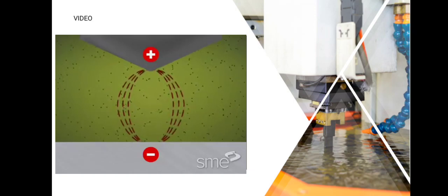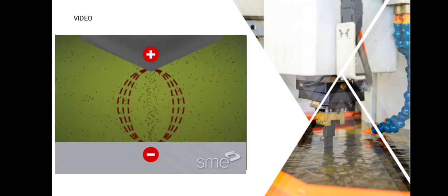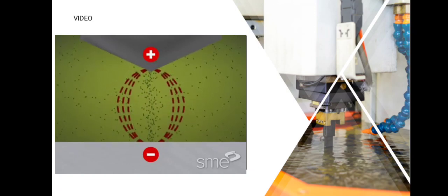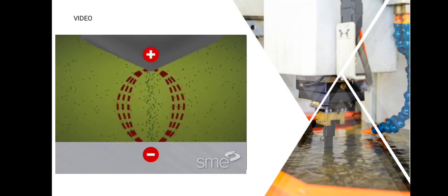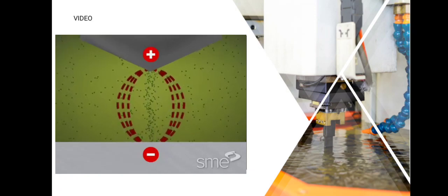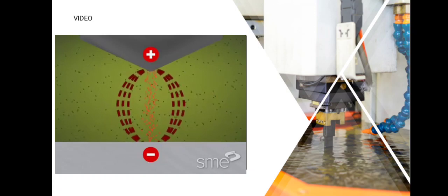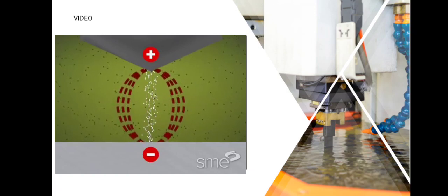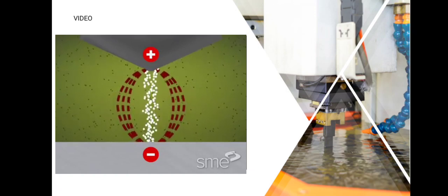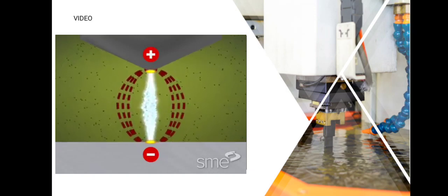Microscopic contaminants suspended in the dielectric fluid are attracted by the field and concentrate at the field's strongest point. These contaminants build a high conductivity bridge across the gap. As the field's voltage increases, this material in the conductive bridge heats up. Some pieces ionize to form a spark channel between the electrode and the workpiece. At this point, both the temperature and pressure in the channel rapidly increase, generating a spark.